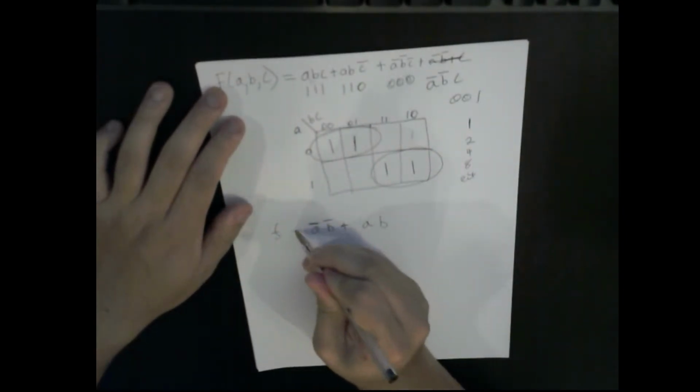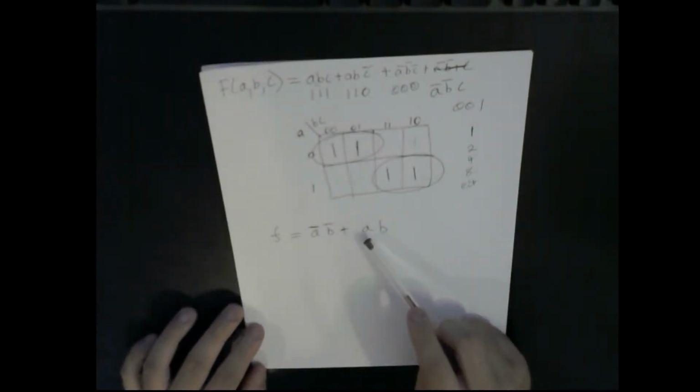So this is our function f now, and this has been simplified. So we have AB and A naught B naught. That's how we do a very simple simplification using K-maps. We can create up to a 4 variable K-map. Those are the biggest types of K-maps you can create and still get through visually. You wouldn't want to create any K-maps bigger than that. They get pretty messy.